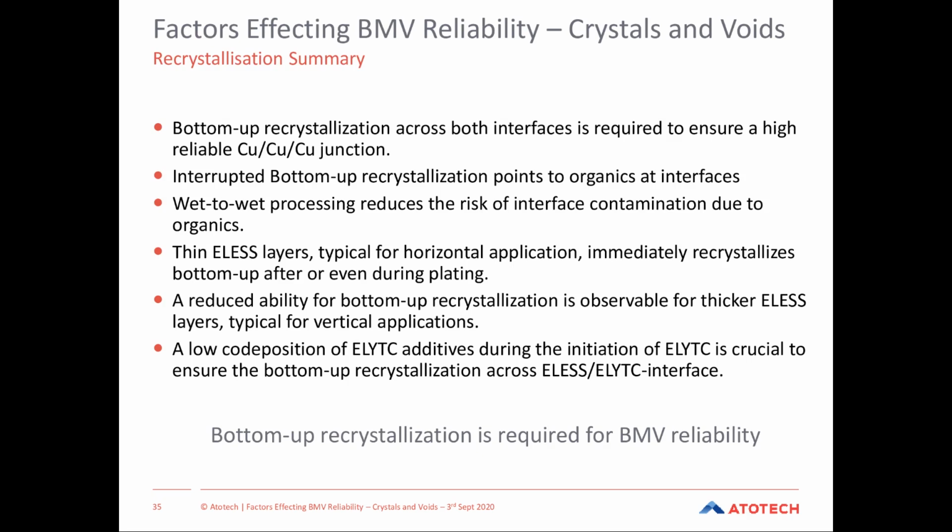We have to acknowledge that both electroless and electrolytic baths do give a degree of co-deposition of the plating additives. This has to be monitored or at least looked at periodically and taken into account when we're looking at nano-voids, because this can impact recrystallization and it can then impact via reliability as well. But the aim ultimately is a bottom-up recrystallization scheme.